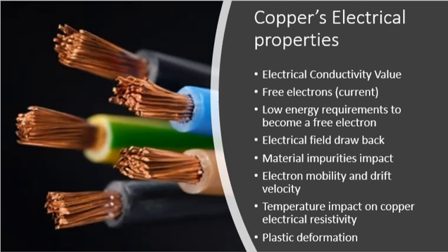When an electrical field is brought within range of free electrons, or makes them, it exerts an electrical force on the electrons in the direction that it's going. This would make the best conductor in the world if that's the whole story. Unfortunately, due to material impurities, even at 0.001%, vacancies in the unit cells, and even the thermal vibrations of the atoms themselves, these free electrons can scatter, lose their kinetic energy, and eventually change direction. Thus, the more impurities and defects in a copper wire, the less conductive that wire becomes.